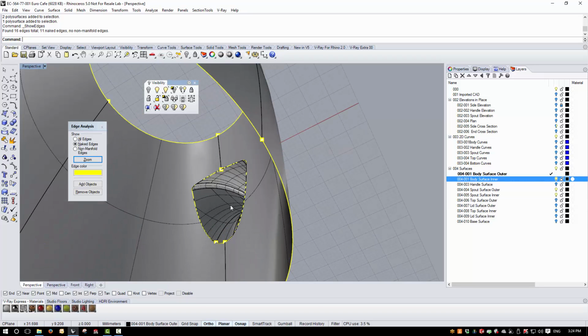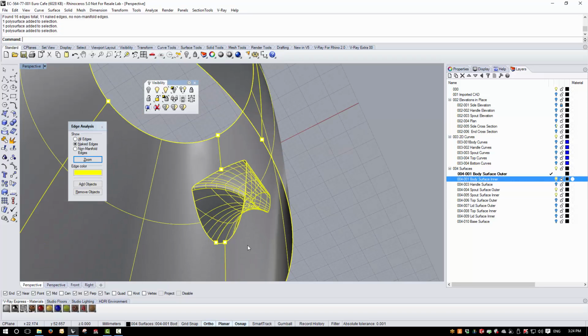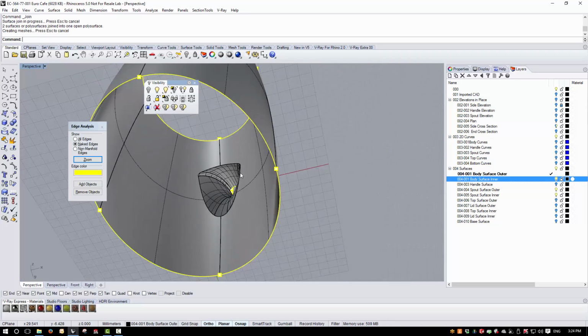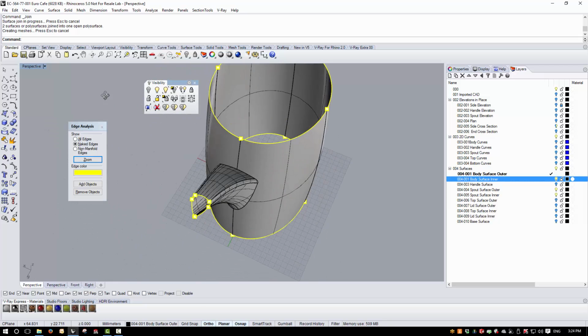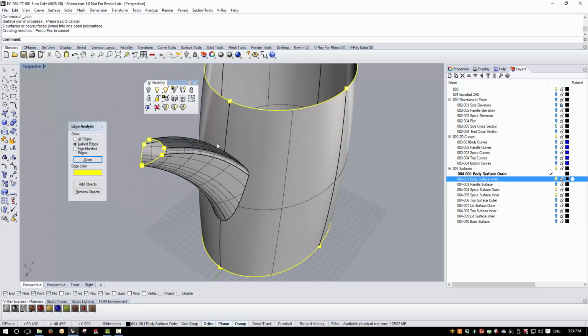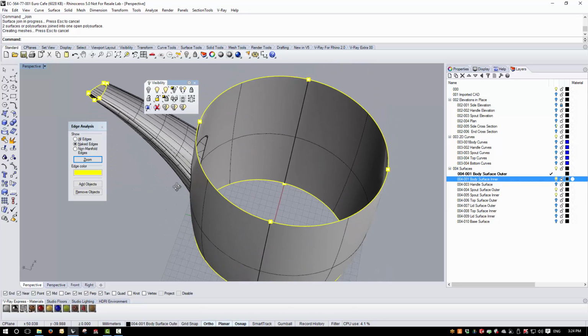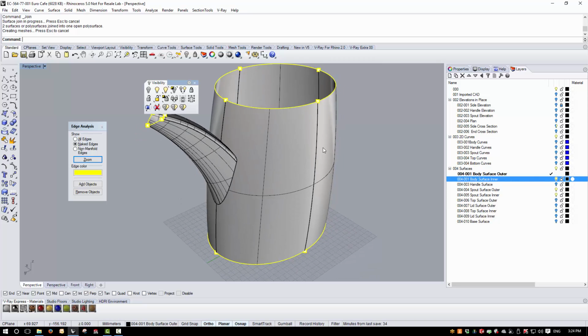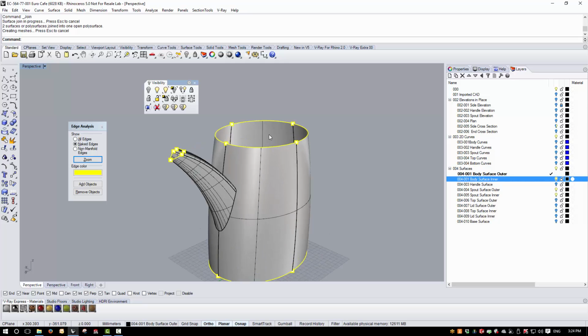Okay, so clearly I didn't join those together in the first place. Right, okay, so that's better. So that's joined correctly. Now we could put a fillet around this inside edge, but it's really not necessary. As I said, we're really using the creating a B surface purely so that we can create a solid model, and more important, so that we can work out things like the lid detail.